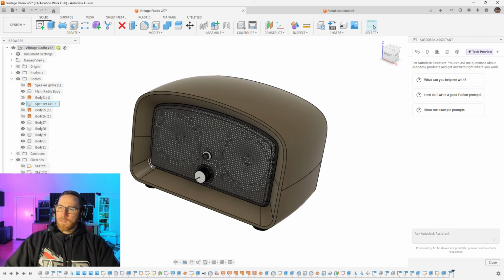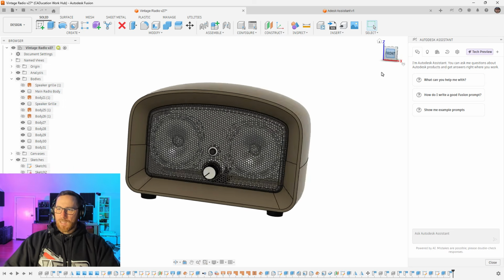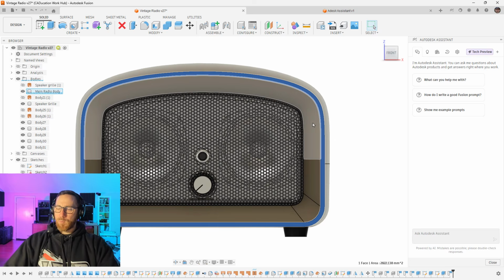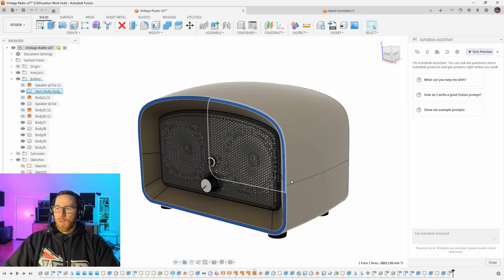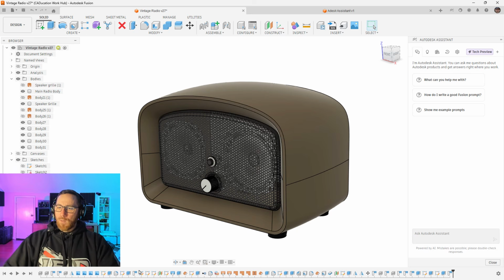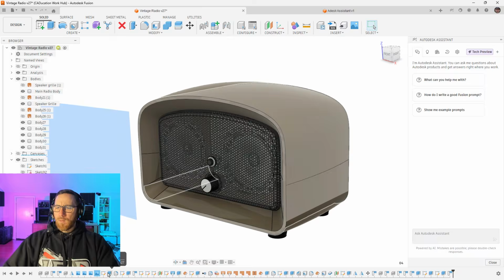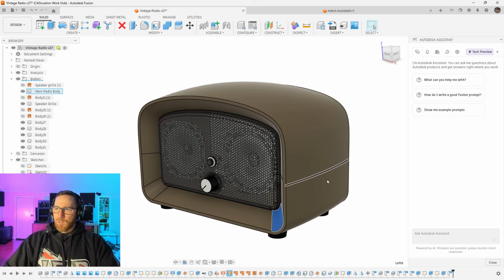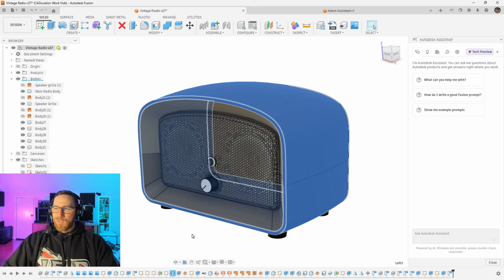And then when I looked at this, I was thinking, okay, well, I need to manufacture it. So I'll create a small flat lip on the front. I'll taper it so that I can print it unsupported. And then use that throughout the process to make those design decisions. After I was done looking at images and deciding the direction, the initial sketch and feature took probably 10 minutes, and going to a more complex one where I'm doing some lofts and some additional work to get the shape took probably another 10, 15 minutes.